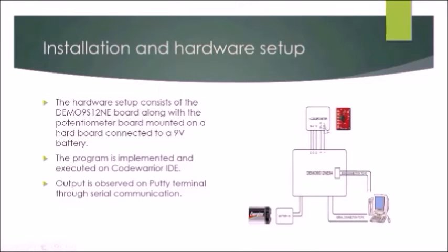The VCC is connected with the first pin of the microcontroller, which has nearly 3.3 volt output. The ground pin is connected with the third pin of the microcontroller, which has nearly 0 voltage output. The three XYZ axis pins are connected with pins 10, 12, 14 respectively.